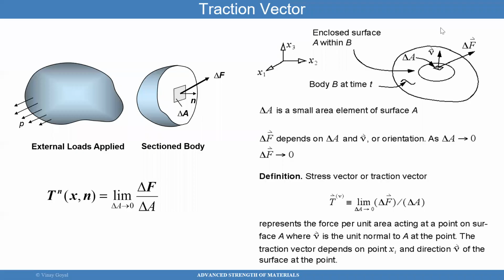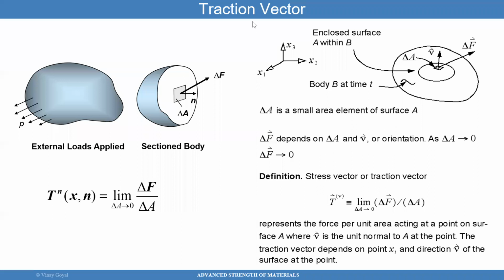Is force? So I will continue. I want to clarify that stress vector or traction vector can be used interchangeably. And the vector of that force, this traction vector T, can be pointed at a direction that's not necessarily aligned with n. It doesn't have to be aligned with n at all. Okay.